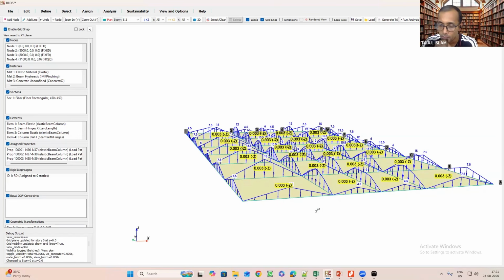Okay, so what we have done is we have used the concept of point loads and applied them in such a manner that all the point loads together represent either a triangular shape or a trapezoidal shape or any shape which you expect from your area loads. Okay, so if you read the TCL script for this load application, you will see a series of point loads applied for a particular member. Okay, and if you add all those point loads together, you'll see it is equivalent to the load intensity of this pattern, or any other pattern applied to a particular member.